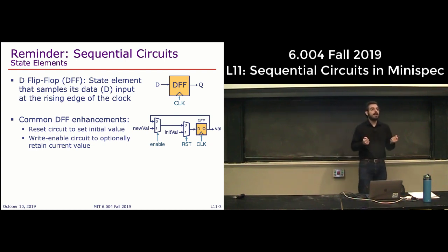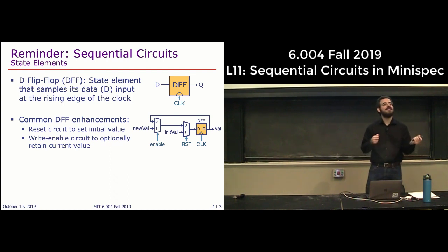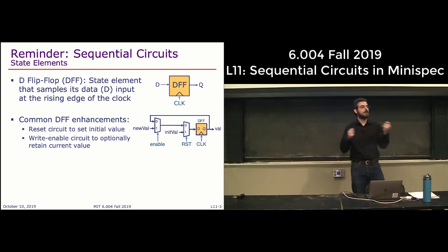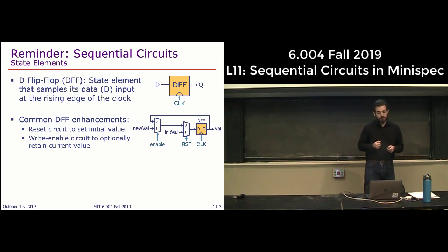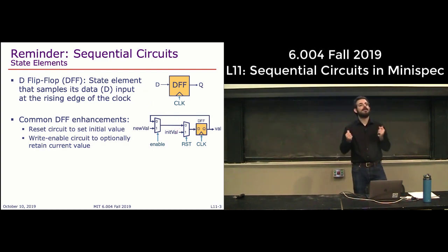And there's no way to design the flip-flop itself so that it reliably goes down to 0 or up to 1. So to set some initial value, there's a little bit of a game that we have to play when we start up the circuit. First we power up all the components, and then for the first few cycles we have this reset signal that we set to 1.